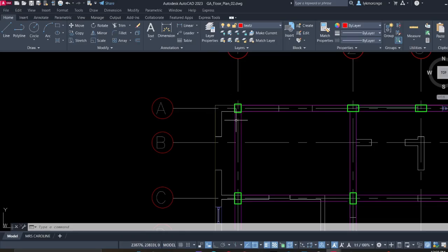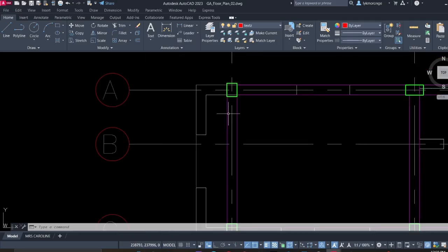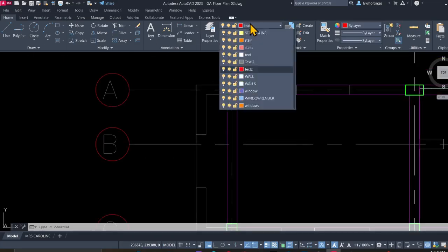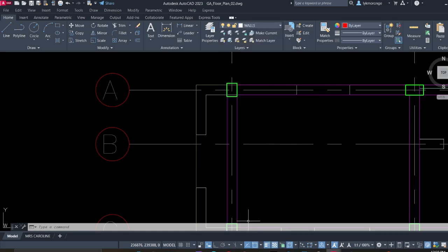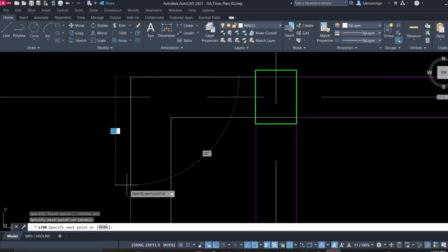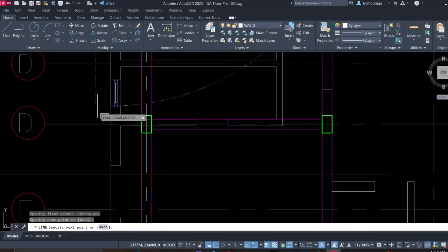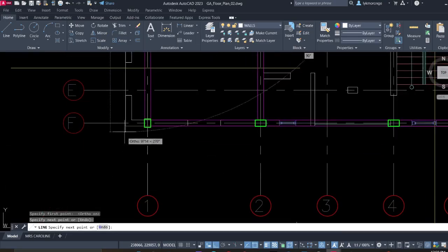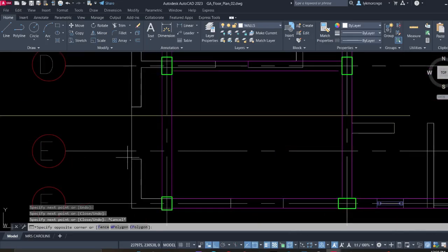So to sort out that, we simply come here. Now change your layer here to walls. Under walls, just click on this, with the auto mode on, and simply come and trace this, just to factor in these. You can always delete these other objects that are here.